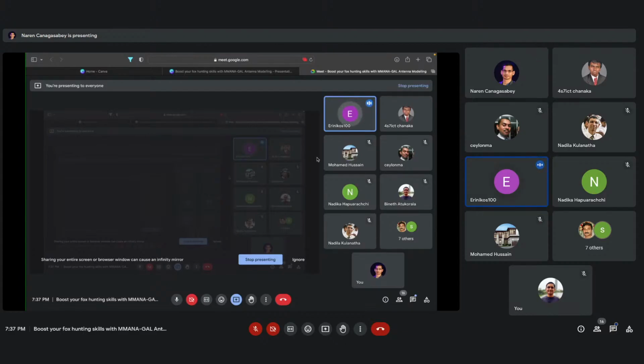There's a function on the wire edit tab where you can break up the element into endless pieces. So take a 20-meter wire and break it up into 2, 3, 4, 5, 6, 7, whatever, and then you can do the tapering. At least that's how I do it. There might be a better way of doing it, but that's the way I do it now. Naren, over to you.